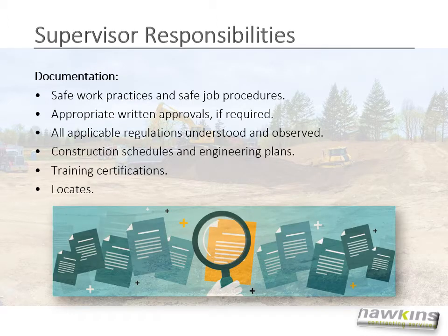Supervisors have a responsibility to ensure that their documentation is in order for ground disturbance activities. This includes having your safe work practices and your safe job procedures in place, appropriate written approvals where required. All applicable regulations are understood and observed. Construction schedules and engineering plans must be available and accurate. Everyone has to have appropriate training certifications, and of course, locates must be accurate and on hand.